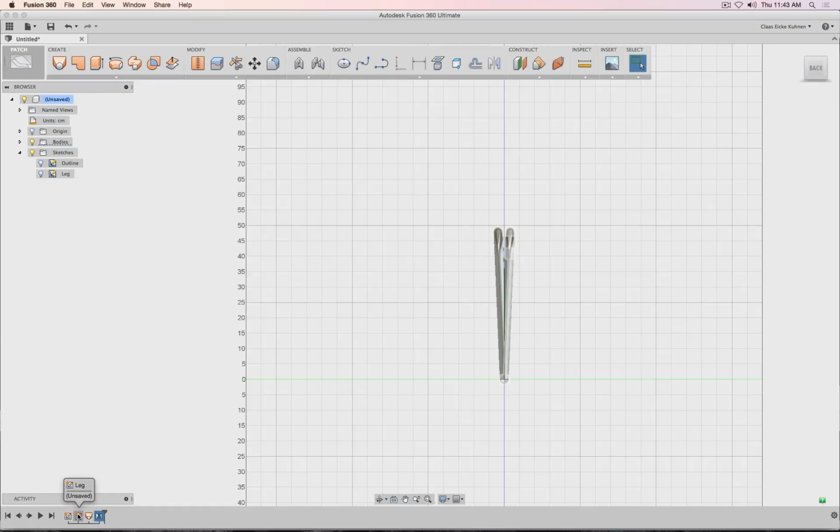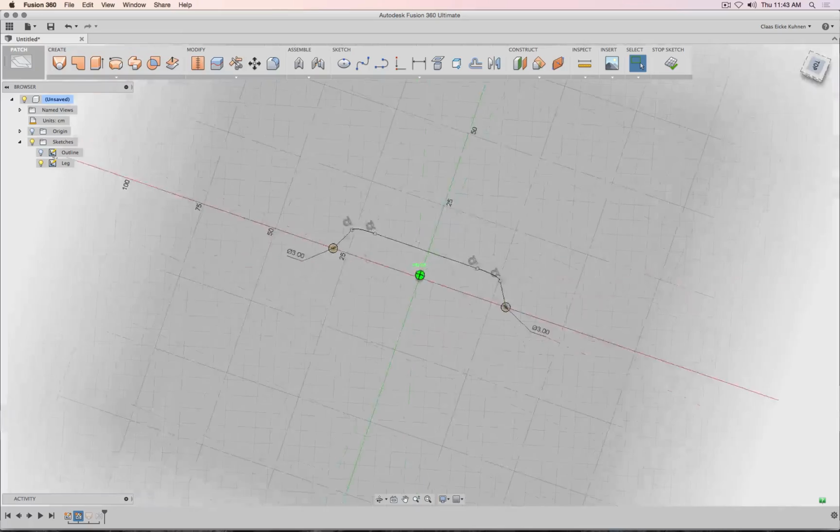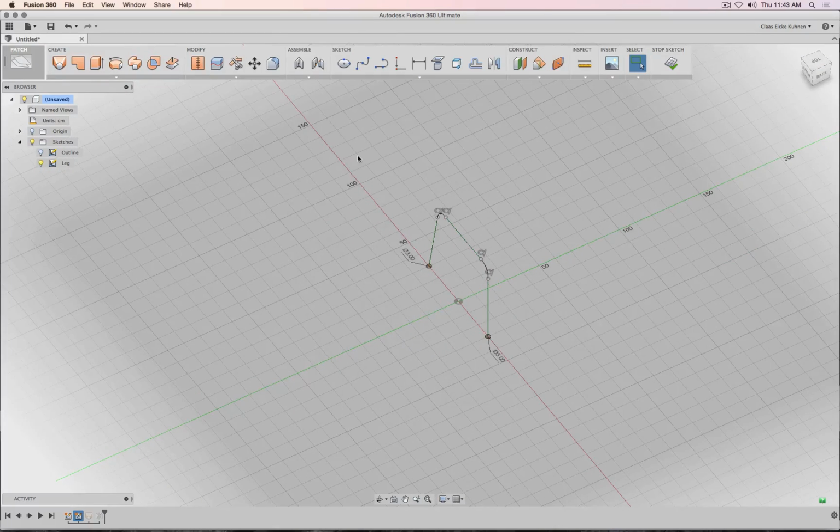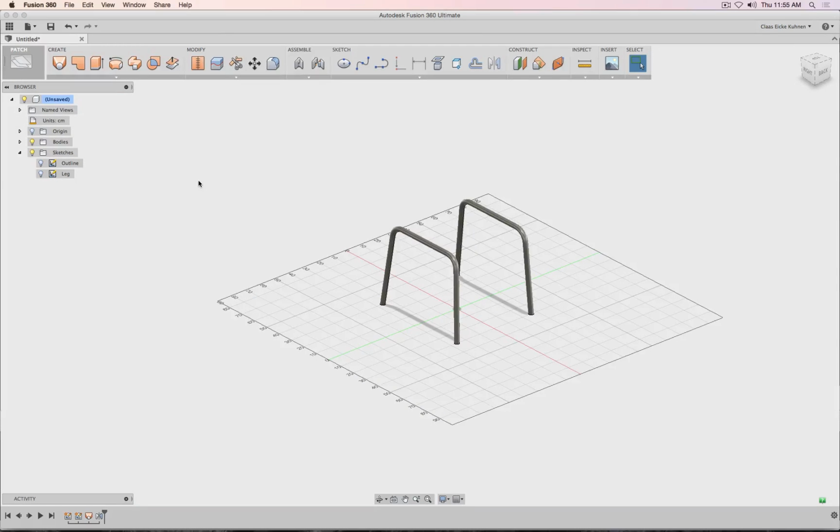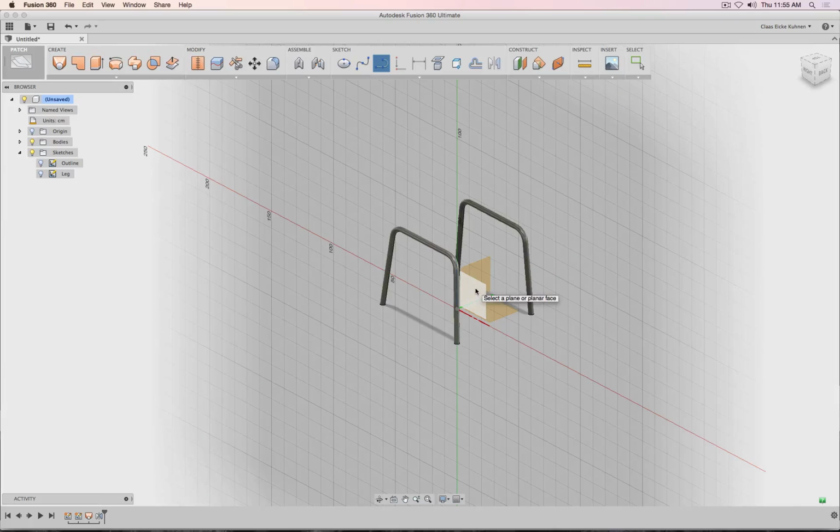You know what I can rather do is simply go into edit, and that's the reason why I created this one on the ground plane. I can select these 3 lines. So our wood shell actually has to sit on something, so we need to put in at least 1 or 2 crossbars. To do this, we can simply make a sketch on the vertical plane between them.